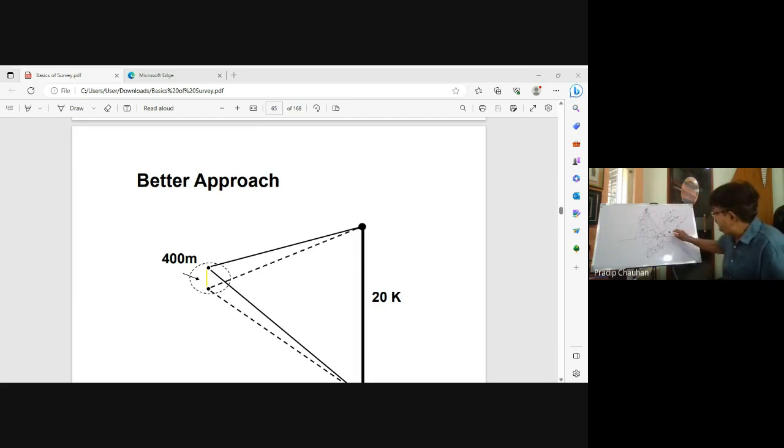Even if there is a tree, there are leaves, and the first ray will hit them and come back. The other may pass through some hole and then pick up the ground. It is known as a second return or third return, and thereby our software allows us to remove all the trees and see the strata or surface underneath, so the topography underneath the tree can also be measured. This drone is moving at a certain speed, and it measures everything.